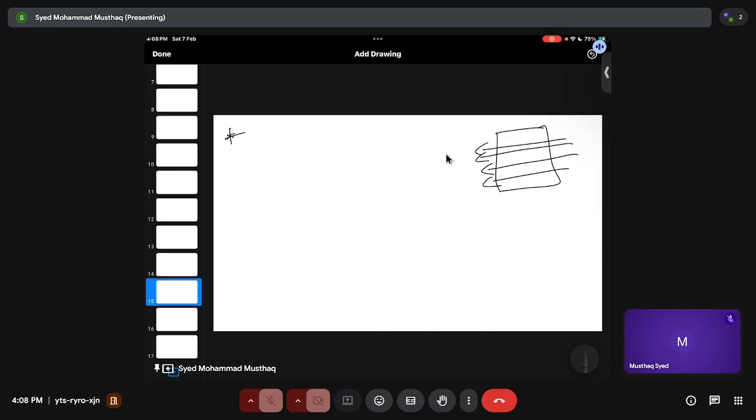It has some certain scattering property, which is not much because it is mostly a transparent liquid, so it does not scatter as much as the different particles. Now I'm trying to introduce some particles. Let's say this is my top view. So this light will get scattered, right? Depending upon this scattering, you have some screen here, and depending upon this scattering, you define your powder particle size. And there are different methods, different formulas that define them.